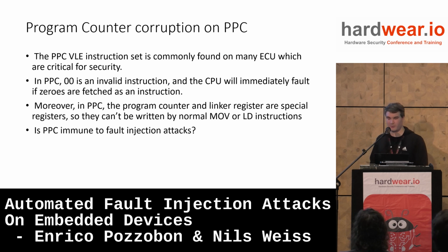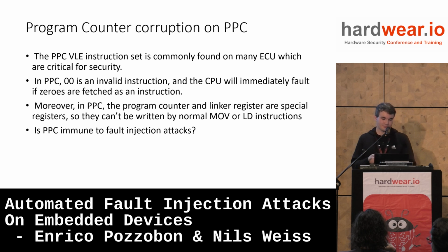Program counter corruption on PowerPC, as I said before, doesn't look like ARM. In ARM, you can just flip a couple of bits to turn any load instruction into a jump instruction to an address that can be controlled by the target. However, on PowerPC VLE, which is an instruction set that was used in our target, and in a lot of our targets, this is not the case.